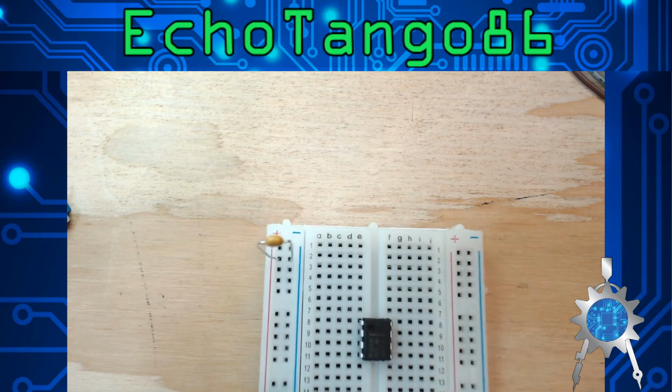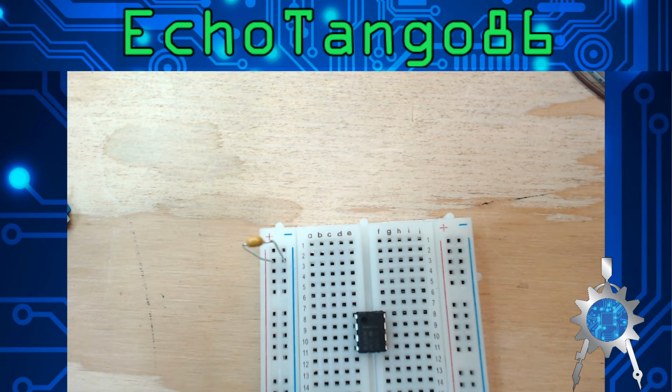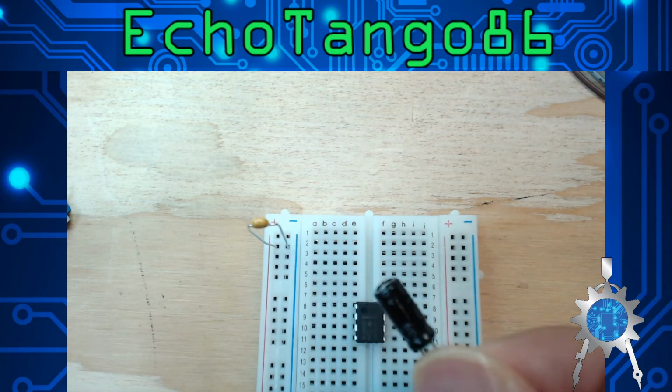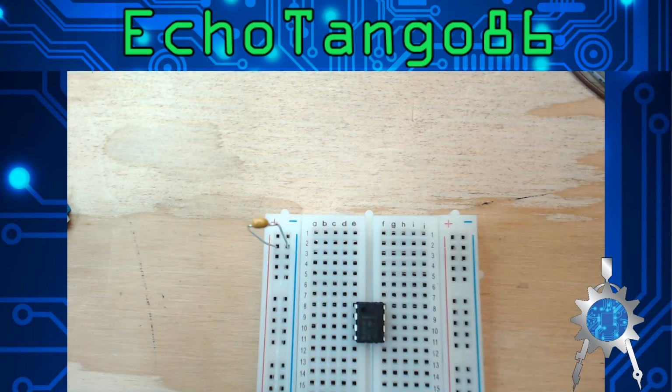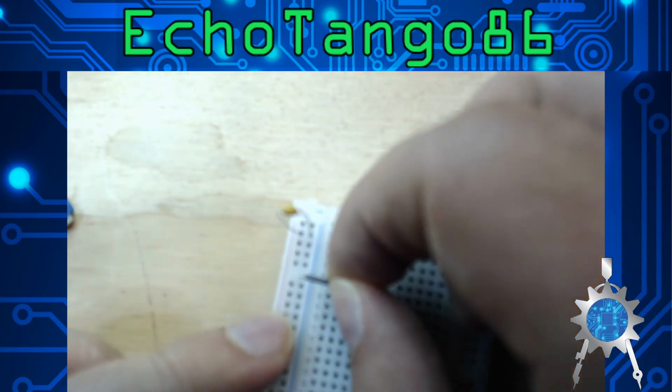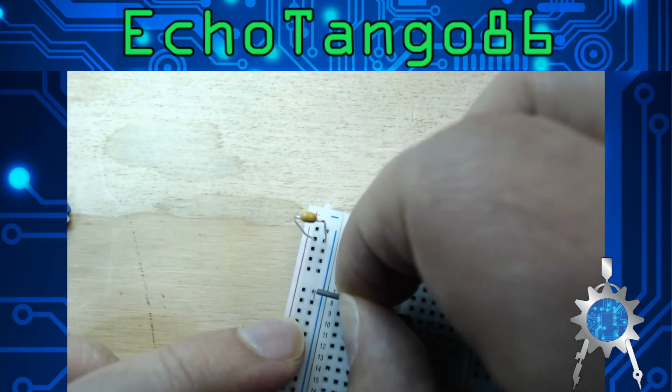So, if your board looks like that right now, you're doing good. Now, we're going to want to get our polar capacitor, and we're going to want to connect up pin 2. Oh, I'm sorry, we forgot to ground pin 1. So, let's do that. Now I have little kits like this that have wires in there to make it just a little cleaner when I'm wiring things up.